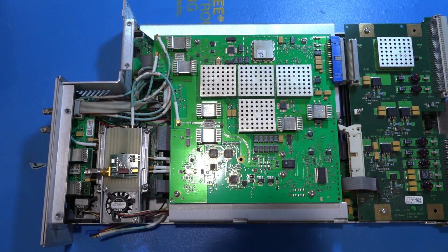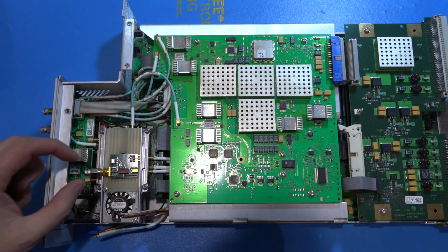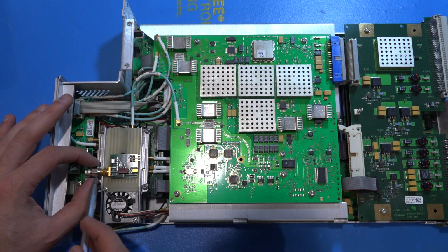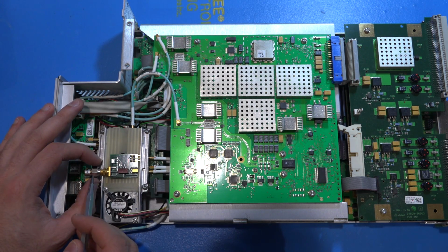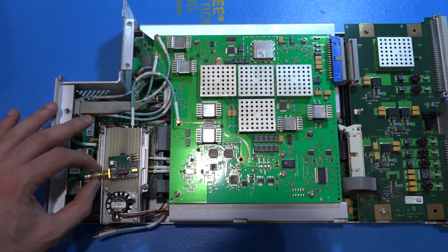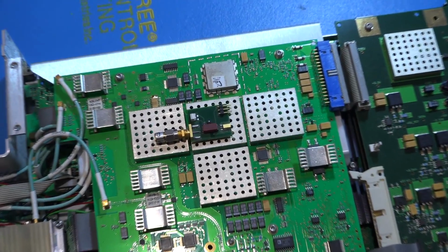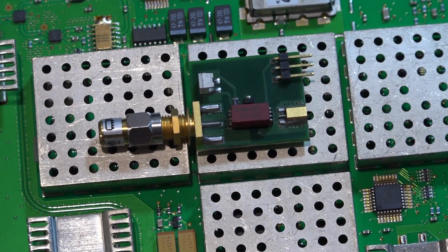So as the manual also says, if there is an overvoltage condition detected on the delay input, the instrument will disconnect the delay input and will not allow you to inject anything into it anymore, and therefore protects it. But if you look at this board, this is an interface board where the input is, by the way, everything here is extremely ESD sensitive. I'm on an ESD mat and everything, so you have to be very careful with this. So this module over here, I'm just terminated into 50 ohms right now, no reason, just so that I don't lose the connector. It's got a relay here. You know what? I think this is one of those things where it's probably best if I zoom into it so you can see what I am talking about. There we go. This is probably better.